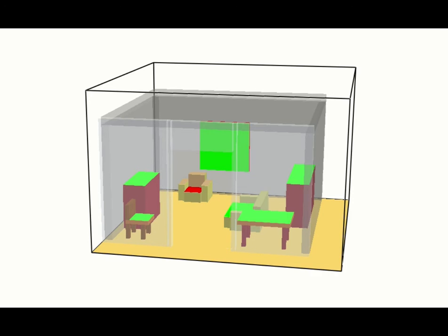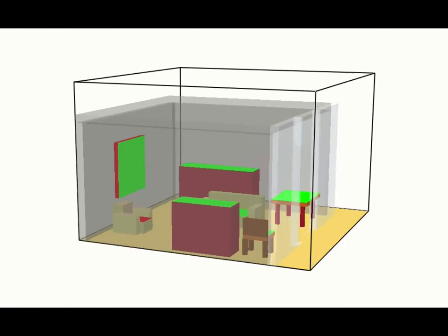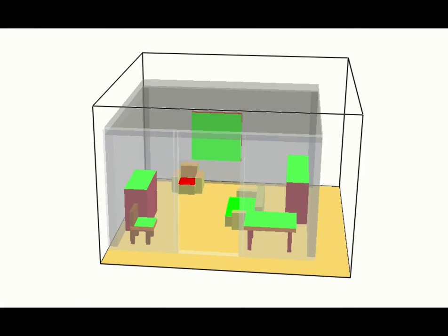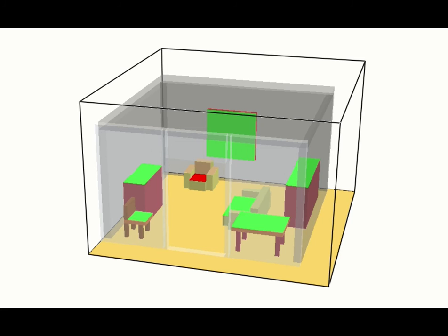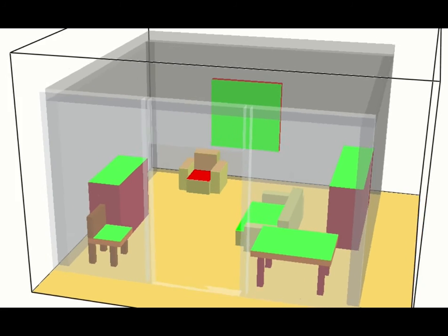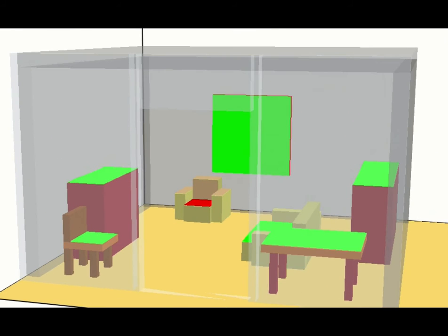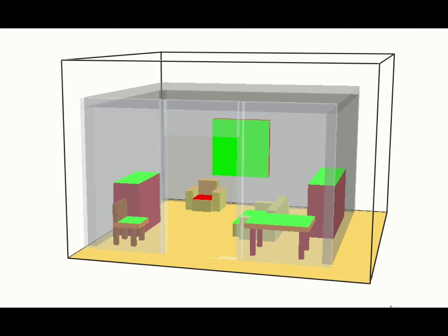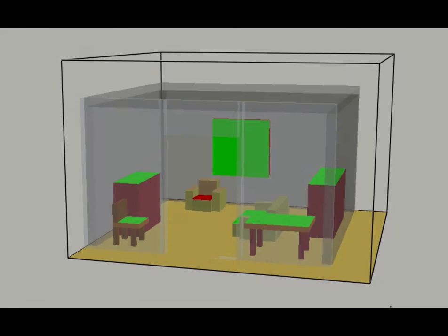The room was recreated three-dimensionally in FDS as close to the real experiment as possible. But due to the absence of actual dimensions and documentation on the material, all the measurements had to be estimated. The fire was set to start on the horizontal surface of the sofa, in the diagram shown in red. It was programmed to spread in a slow t-squared manner, as would be expected in a fire of this sort.